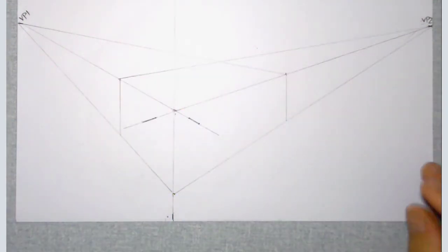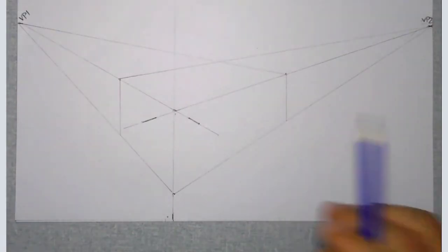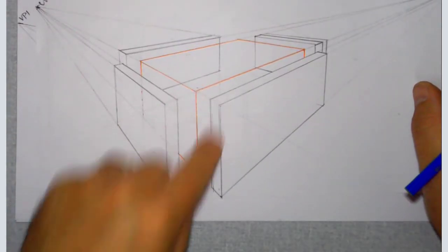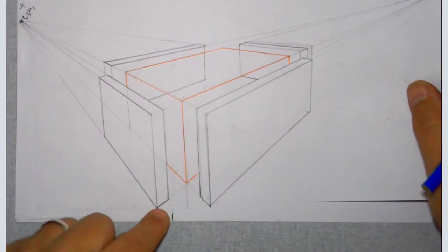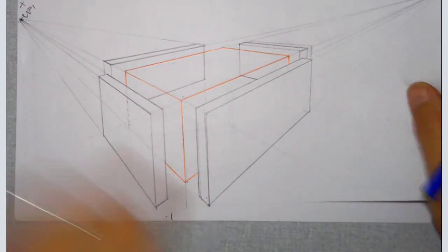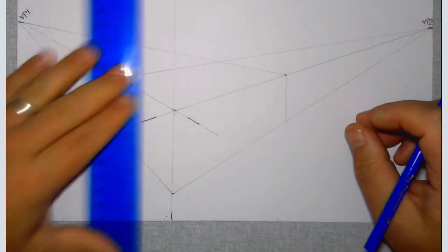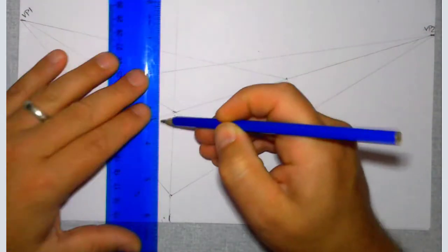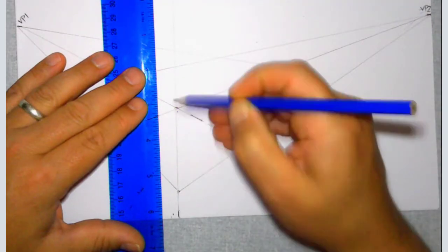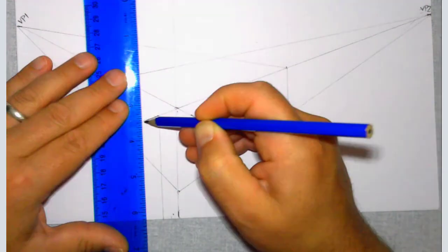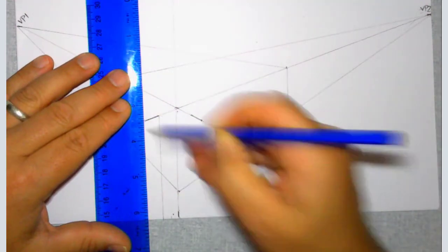Right. So what we're going to now do is we're going to plot down to create the front face here and the front face there. So those are going to just be vertical lines. I'm going to run them right off the bottom of the page. That's absolutely fine. And we'll be using this red bit here to chop them off. So let's just draw from each of those 2 points, there and there, straight down the page. Again, this is one of those ones where you check that you're 90 degrees off the page, or vertical remains vertical. Checking against that line.